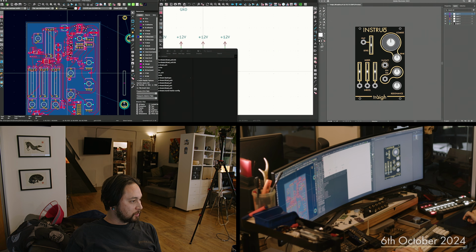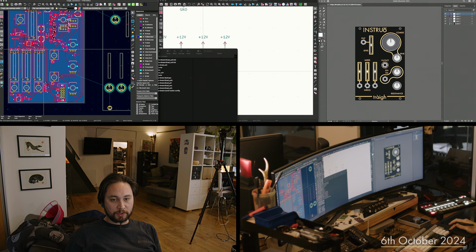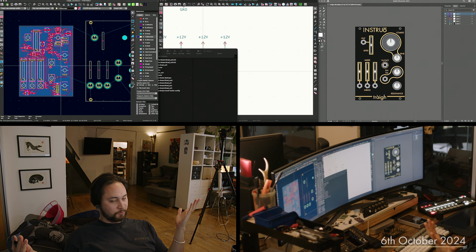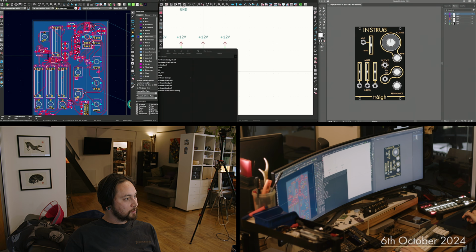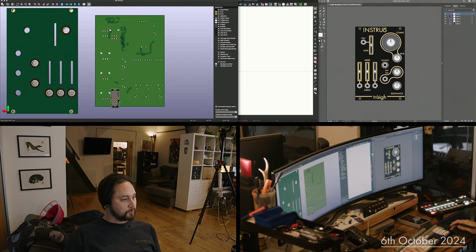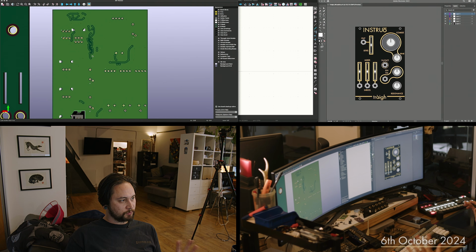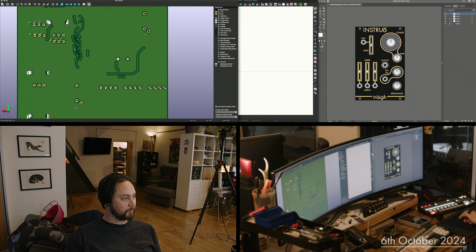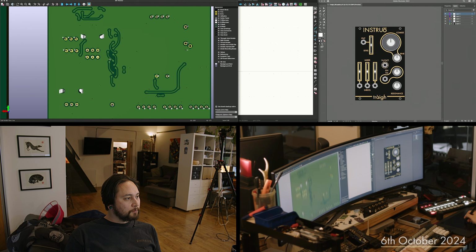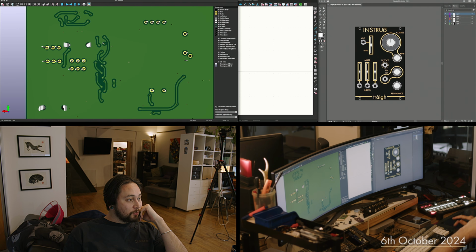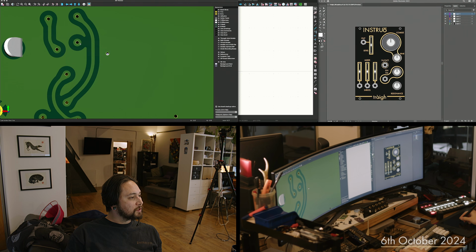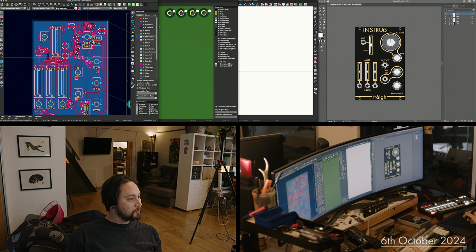Next up's faceplate, and then I can order a prototype, test that out, and hopefully that's a filter design, which is cool. So yeah, that's the process I do these days with KiCad for doing a PCB layout. Although more recent projects I'm starting to use 4-layer boards a lot more for denser or mixed signal designs, which is a different technique in itself, but a lot of the times I can get away with, oh, that's weird, why is that just a random via on this one, where is that?